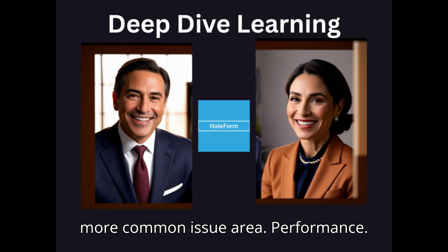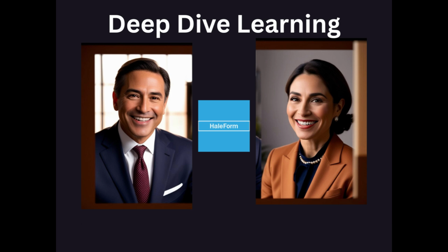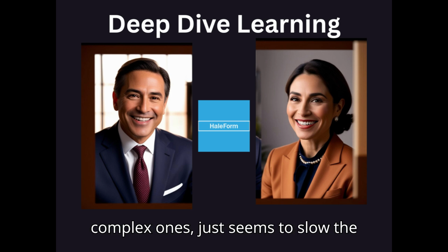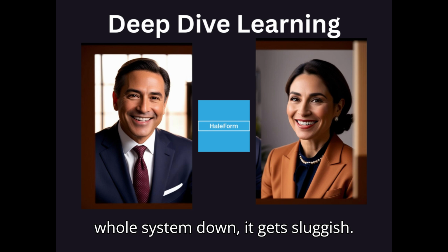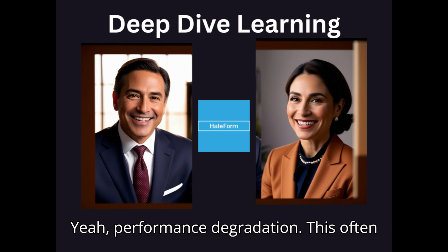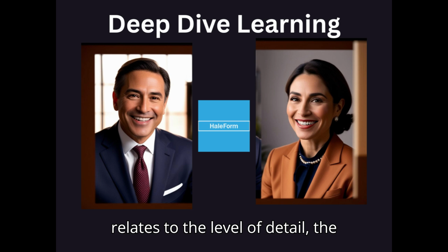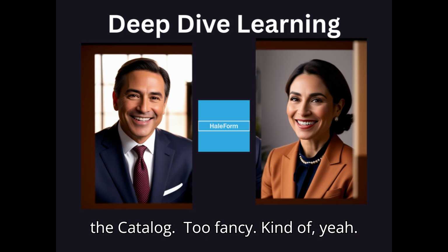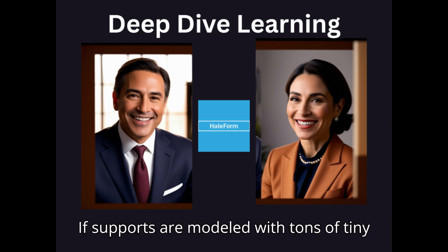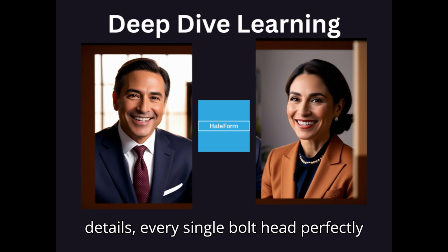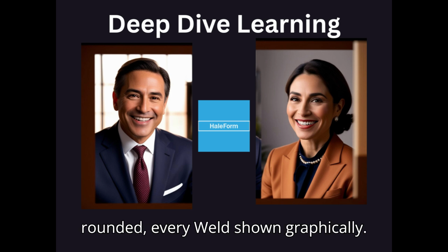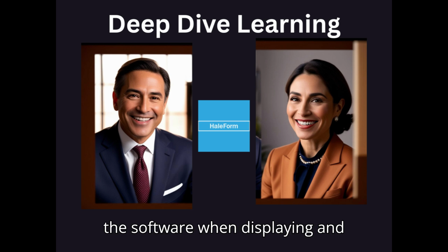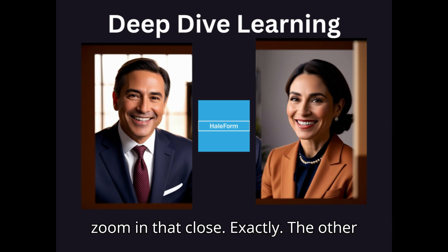Okay, one more common issue area. Performance. What about when placing or modifying supports, especially lots of them or complex ones, just seems to slow the whole system down? It gets sluggish. Yeah, performance degradation. This often relates to the level of detail, the geometric complexity within the support component models themselves in the catalog. Too fancy. Kinda, yeah. If supports are modeled with tons of tiny details, every single bolt head perfectly rounded, every weld shown graphically, that adds up. It increases the load on the software when displaying and manipulating them. Even if you'll never zoom in that close.